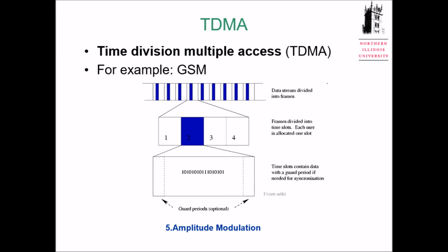So this is the data or information transmitted through the channel. You can find it has small frames, or small blocks. If we enlarge this portion, we get 1, 2, 3, 4. For example, I only support 4 users. User 1 always uses slot number 1 in this big frame.